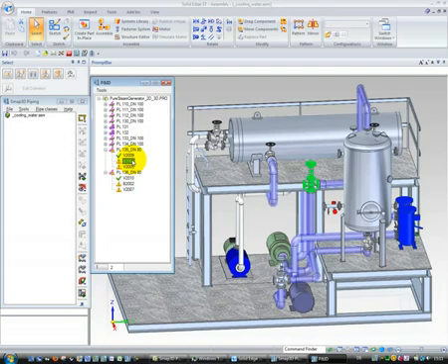Now we also have the requirement to bring this component into the 3D assembly we actually work in. And because a vessel normally does not belong to a pipe class specification, we have a different way to place it. The normal way to place some kind of outer equipment, for example a vessel, is to import it or to model it in Solid Edge and then to place it into the assembly.